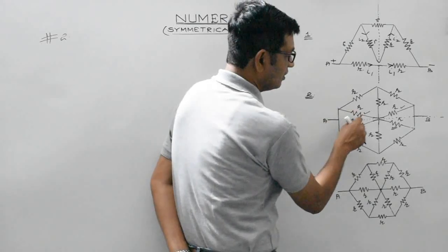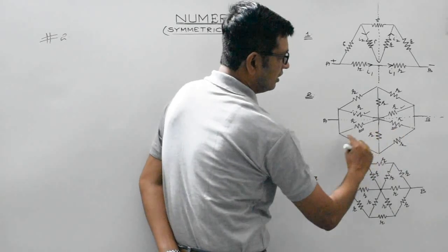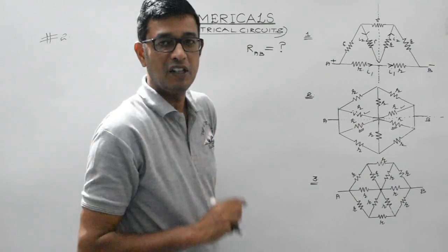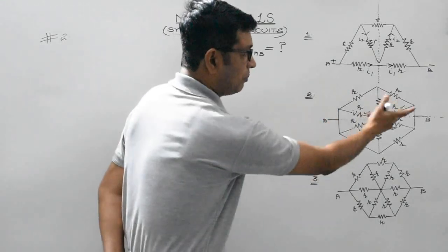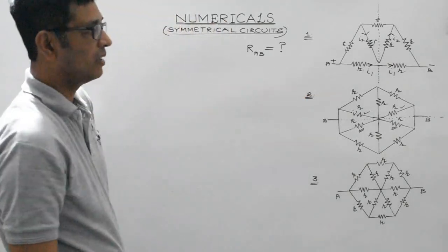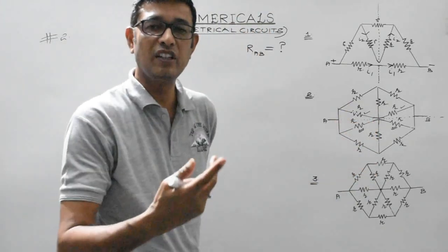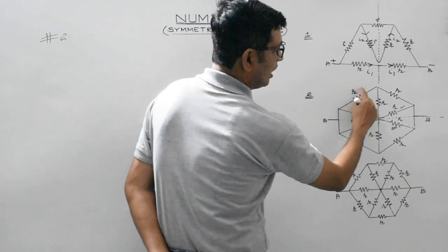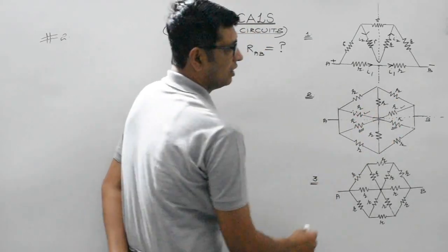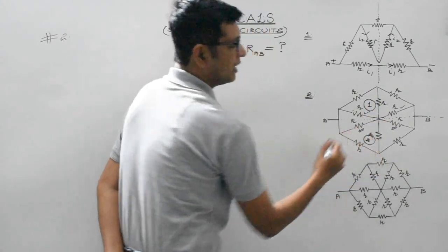Then what happens is, these two are in series, so same current will flow through each of these two resistors. So the condition gets fulfilled that current across the symmetrical parts of the circuit must be constant, right? So it can be modified in this manner. Now look students, it is the case of two Wheatstone bridges which are already in the balanced condition. Look, R by R is equal to 1, and here R by R is equal to 1. These are the ratio arms. Therefore, this is the first balanced bridge, and this is the second balanced bridge.